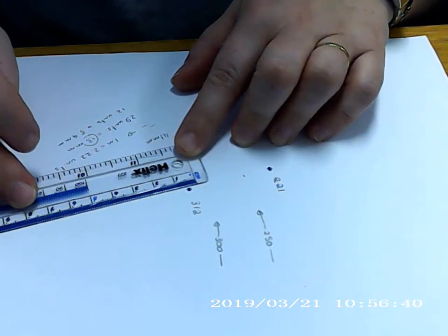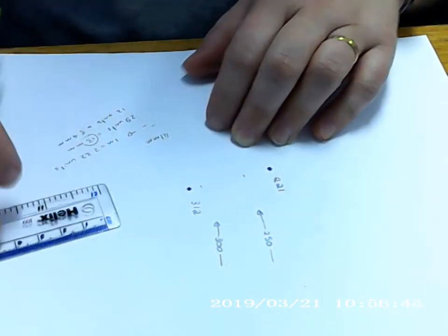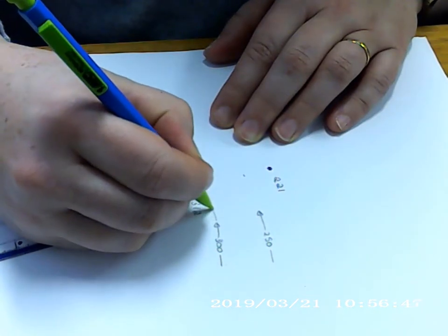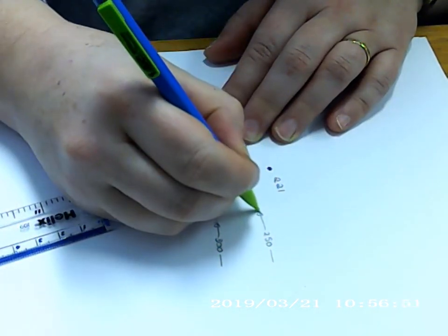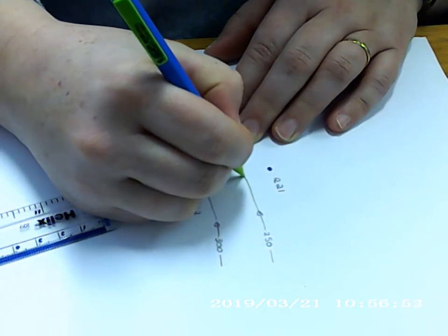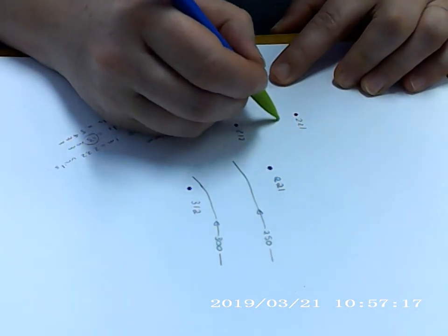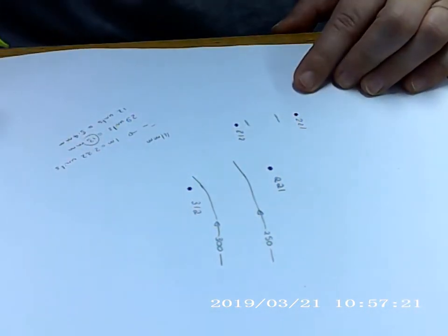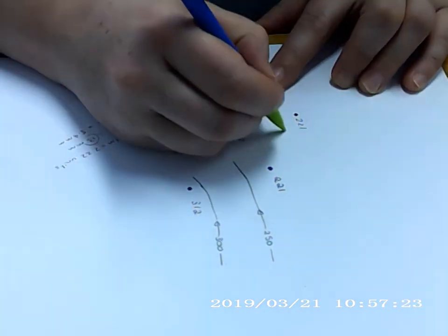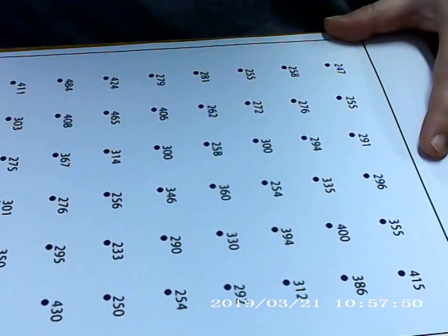However, this takes a lot of time, measuring and then drawing and so forth. It is often easier, and of course much quicker, to guesstimate where the contours should sit and then sketch them in. You will often find that in order to create smooth, realistic contours, we need to be a little loose about exactly where contours are located between data points. This is because our basic assumption of even gradient between points is actually incorrect. Slopes are usually not even between data points.